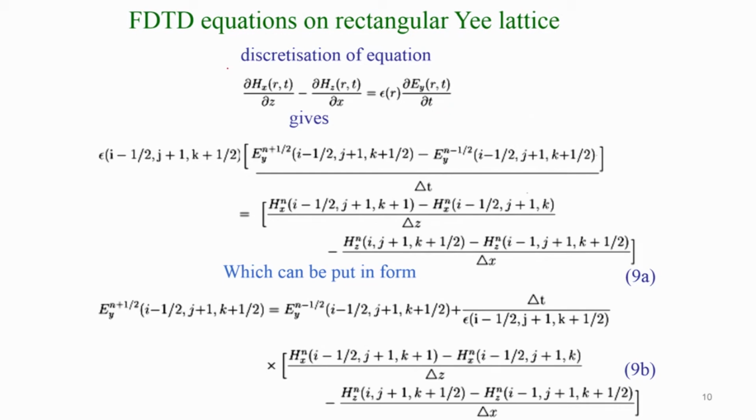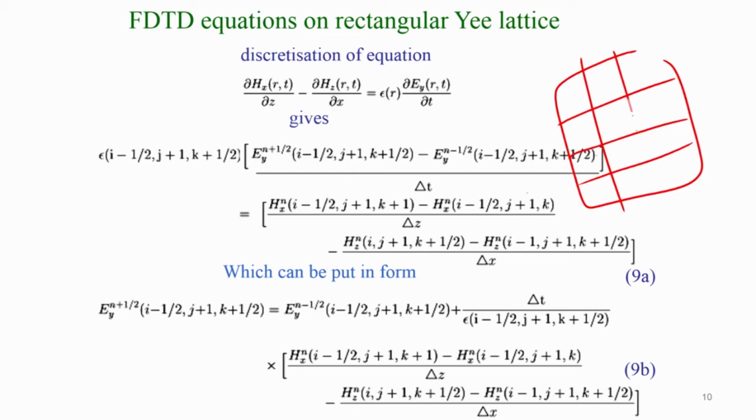Basically, this FDTD method discretizes the field in both space as well as time coordinates using different finite difference techniques like central differences, and so on. We need to divide the entire area of operation into very fine grid points, and at each point you define the field at some particular point and express it in terms of the neighboring points.